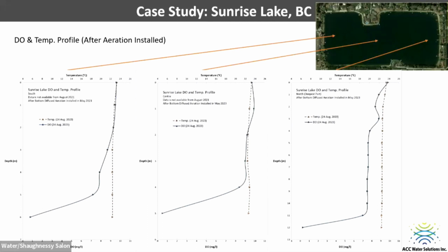The choice that they had was, okay, we can put in an oxygenation system. It'll cost you 4 times as much money. Can you live with 2 weeks per year where you're going to drive some poor water quality, at least for the first probably 3 to 7 years of operation? It's hard to predict that. There's a huge amount of organic sediments.